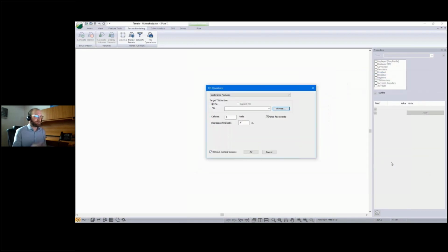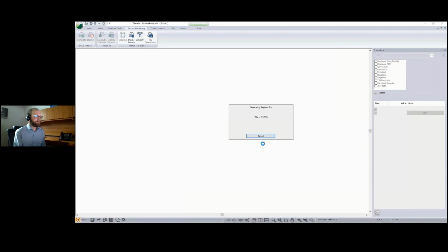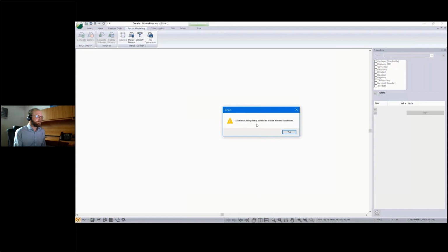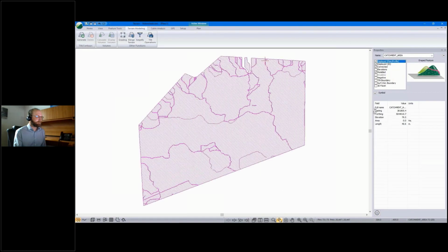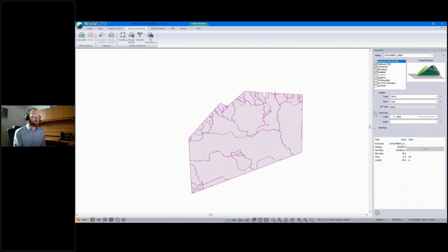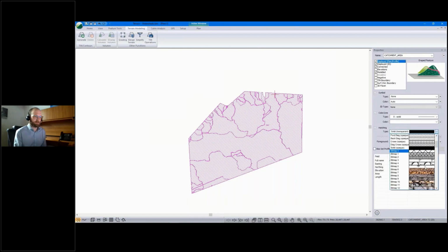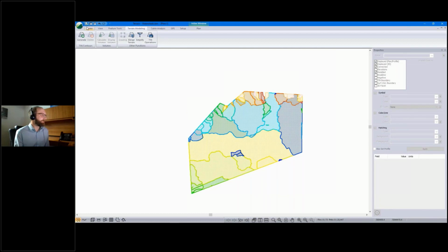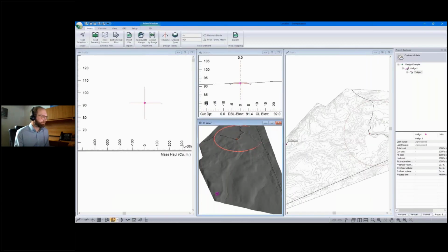And I'm going to reference my topo surface to generate this. So it'll run through. It takes a little bit to calculate. And there we are. And I'm just going to change the symbology here. So rather than transparent polygons, I'm going to change it to suit my personal preferences and make the line type around them a little more obvious so it shows up on your screens instead of just mine. And once again, I'll save that and dump it in as a background.